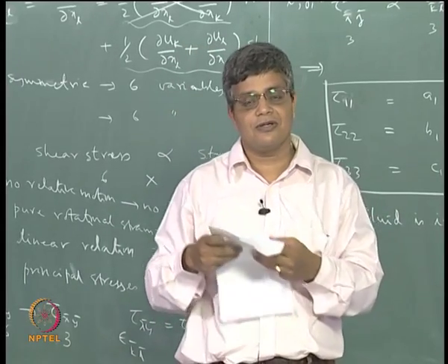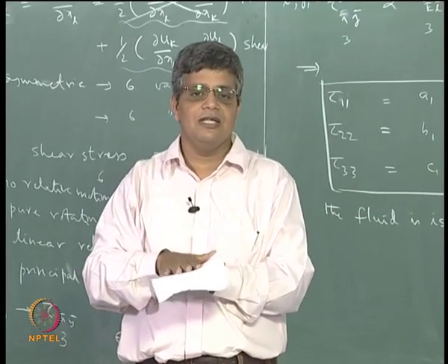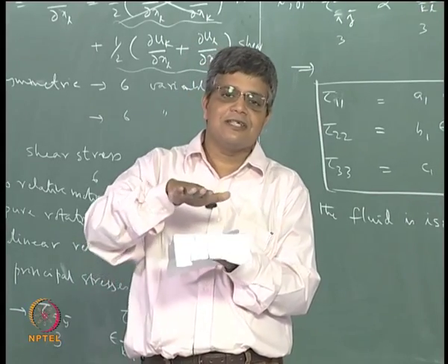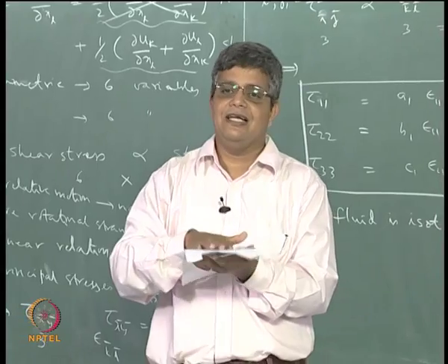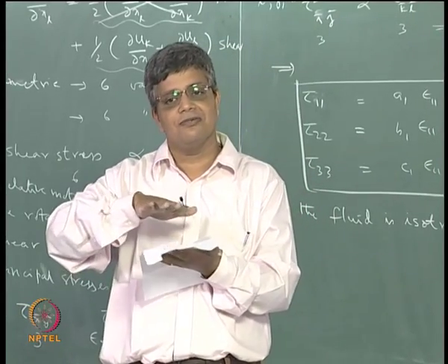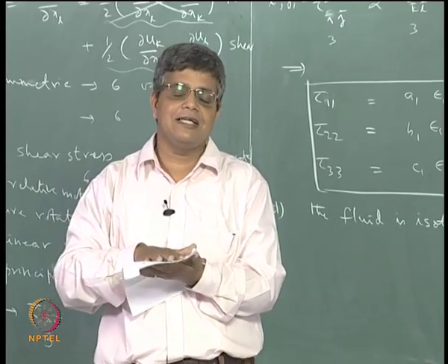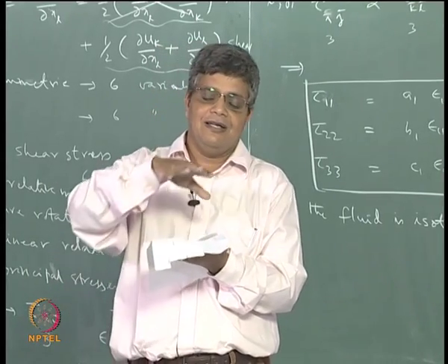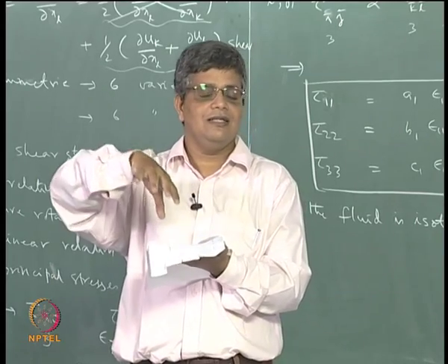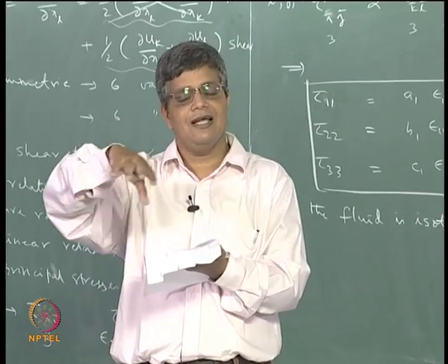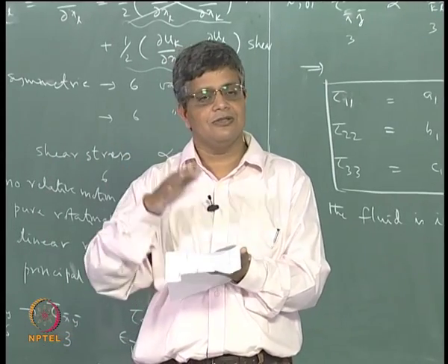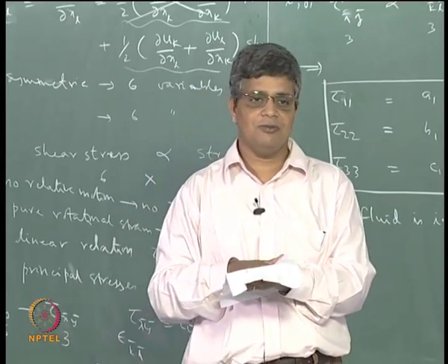So if your material is constituted in such a way that it has some intrinsic fault lines, intrinsic strength patterns and intrinsic orientation of chains and all that, in such a case you can expect forces applied in certain directions to produce certain strains, and applied in a different direction to produce a different amount of strains. So such a material is not an isotropic material.